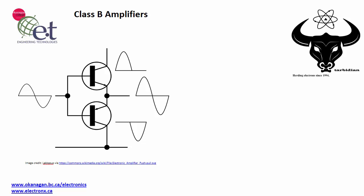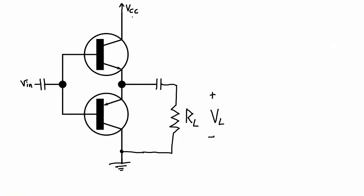I'm Dave Williams. In this video, I'm going to explain the way that Class B amplifiers work. I have redrawn that BJT circuit down here and I've added a few components, and this is a Class B amplifier. It's an example. There are other different types of circuits, but this would be a push-pull Class B amplifier with an NPN transistor connected to a PNP transistor.